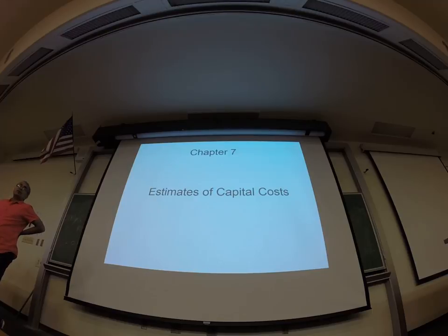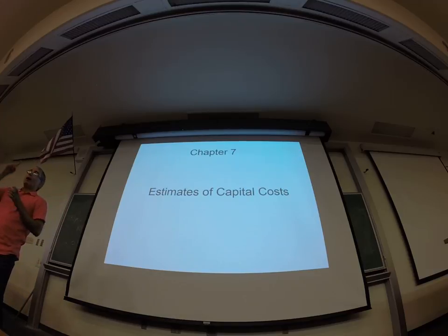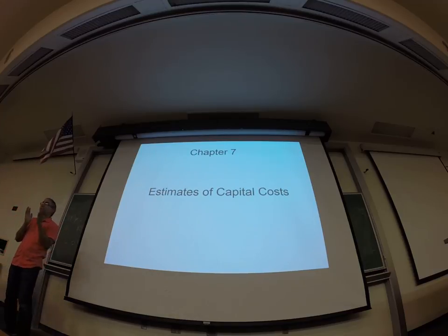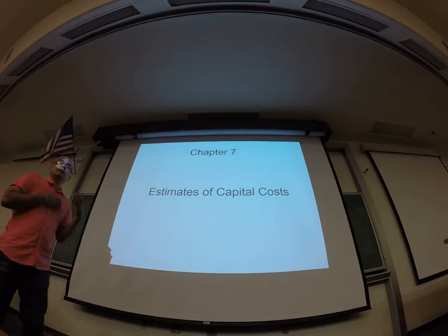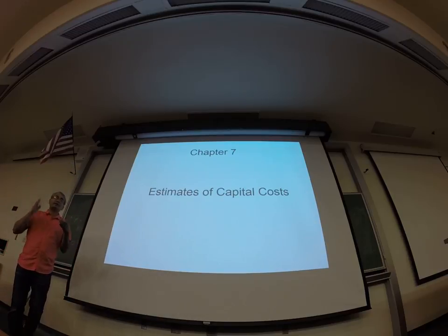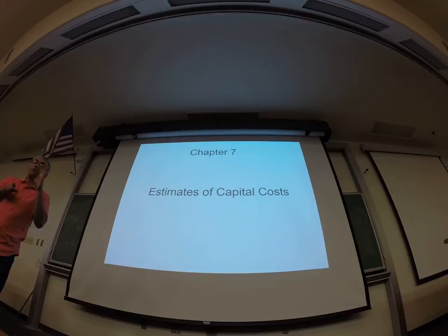Right, you use the scale factor, right? And you use a cost exponent. What's the cost exponent for chemical industry plants? No, that's the chemical engineering plant cost index. So it's a cost exponent. Power 0.6, right? You need to remember that. If there's only one thing to remember from costing, you need to remember that chemical engineering plants typically scale as capacity to the power 0.6. If anybody's going to ask you a costing question in an interview, that would really be it.